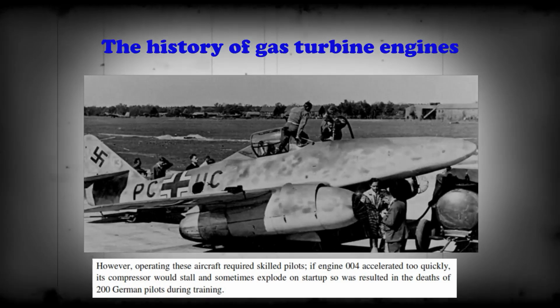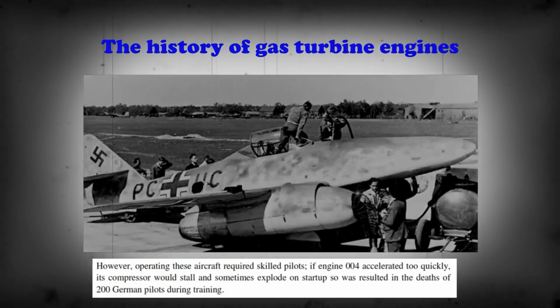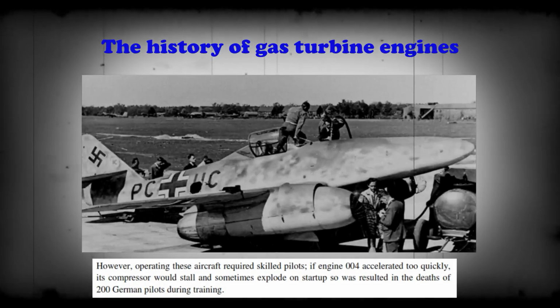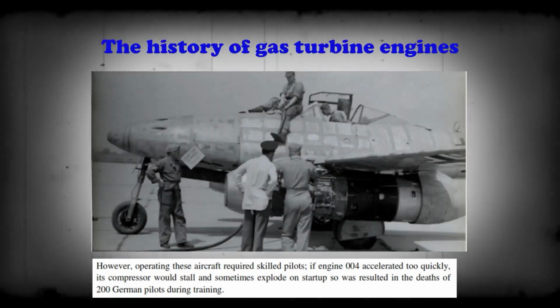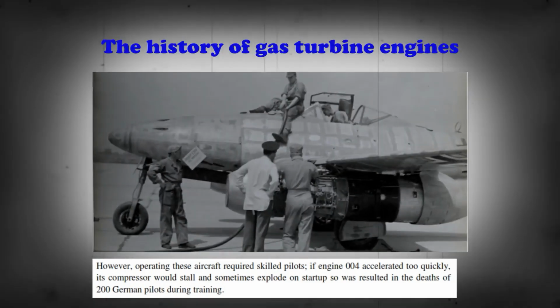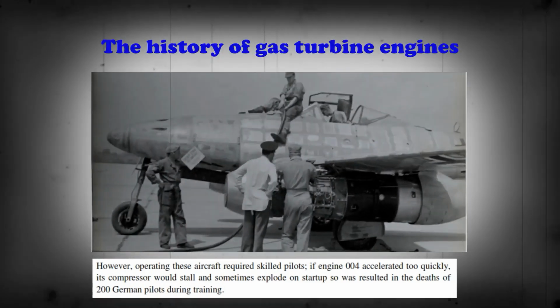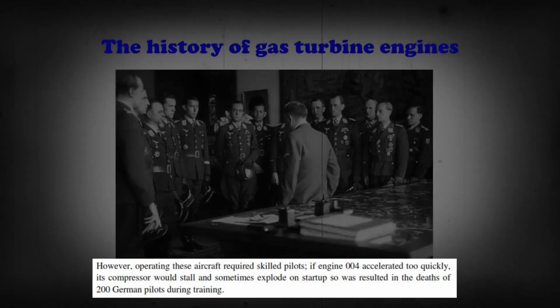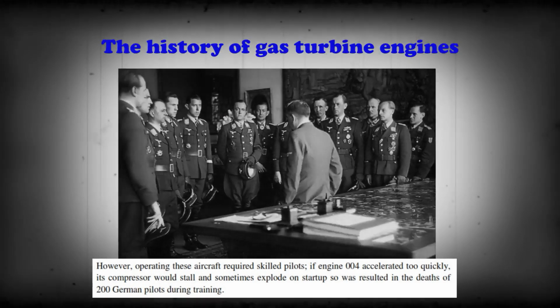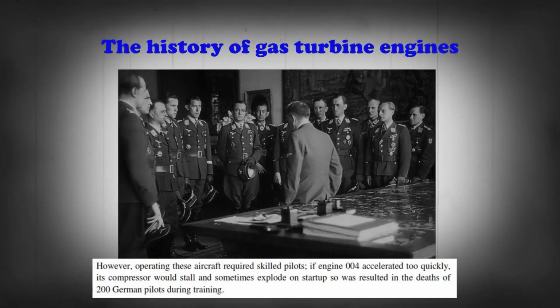However, operating these aircraft required skilled pilots. If engine 004 accelerated too quickly, its compressor would stall and sometimes explode on startup, which resulted in the death of 200 German pilots during training.